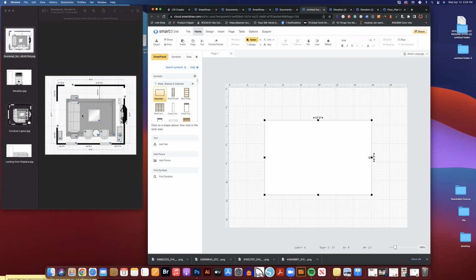Carissa and Olivia sent me their floor plans. So what I'm going to do is show the wall and how to do it with their floor plan. So that'll help guide you guys. So for example, this is Carissa's, I believe. So what I'm going to do is first do the wall with the opening. So my 8 foot is going to stay because that's the height. And then I need to change my width to 13 feet 7 inches. And you get that measurement from right here where it says 13 feet 7 inches.